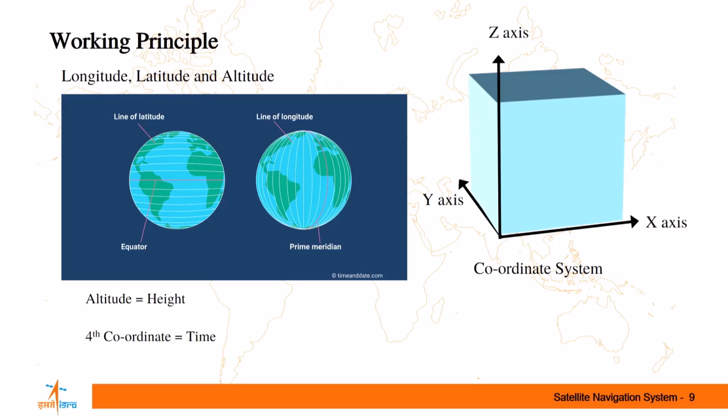So what happens is that the accuracy and the precision of the two clocks has a synchronization issue, because they have different accuracy, different precision. So there is a fourth unknown parameter which is called the clock bias. So the problem which gets crystallized is like this, that we are interested in 4 parameters, basically the position of the receiver, which is defined by the longitude, latitude and altitude, and we have to resolve the clock bias also. So the fourth unknown parameter is the clock bias.